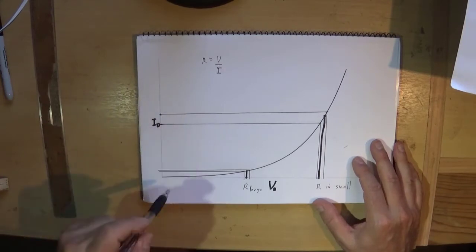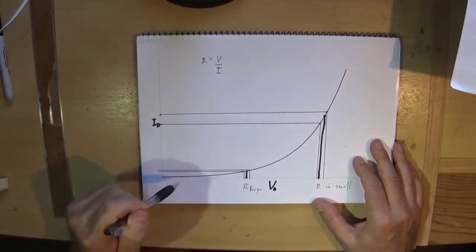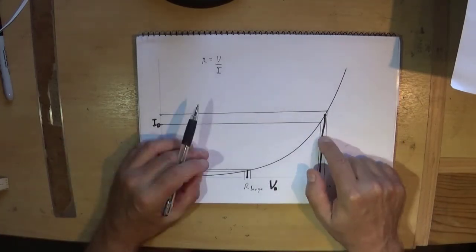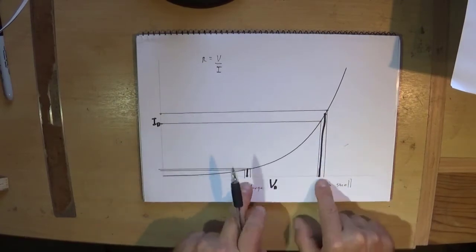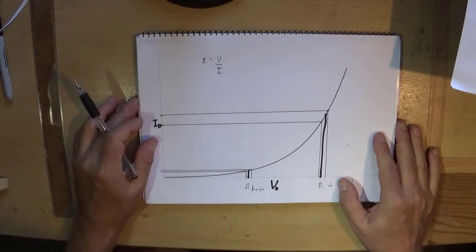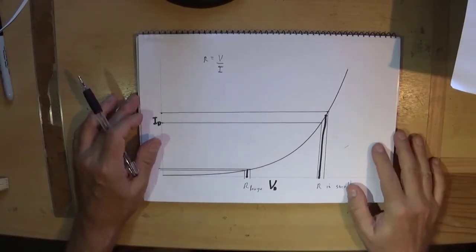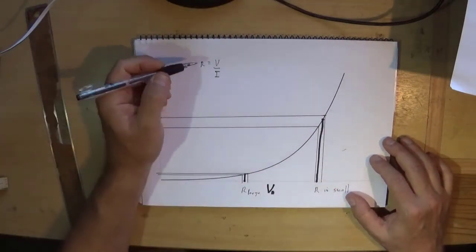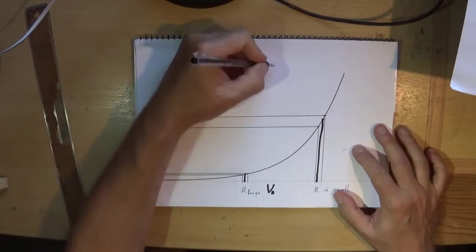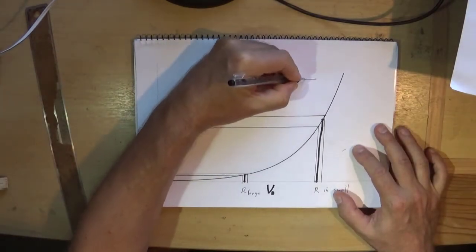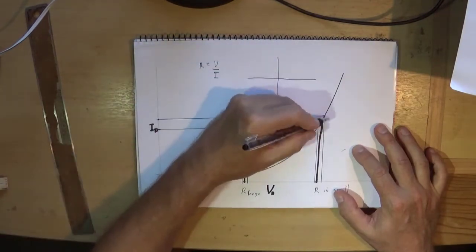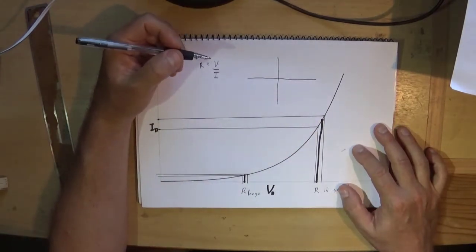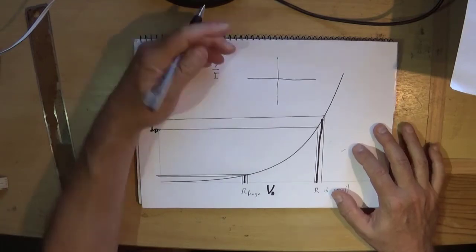And in addition, because this curve is exponential, we can arrange it so our filter cutoff frequency changes at 1 octave per volt of our bias, which is what we want. So we are using this system to make a voltage controlled resistor in effect. But a resistor, if we plot just over our little signal range, a resistor is linear.